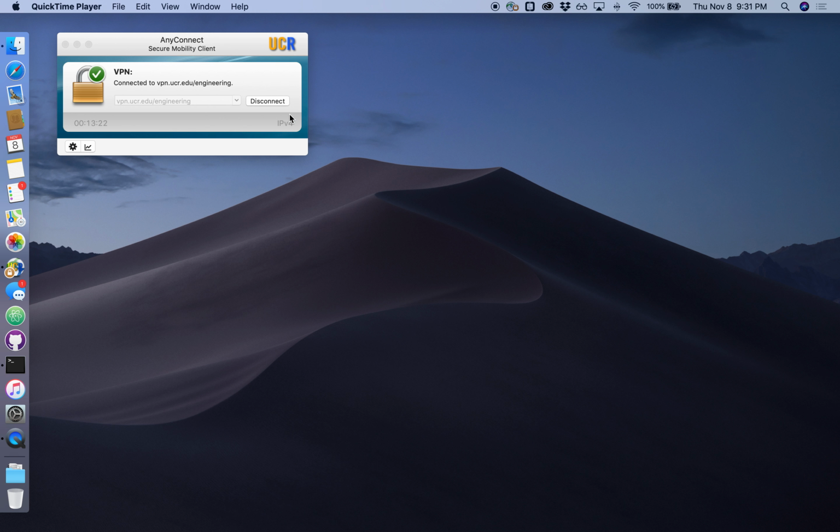Hi, this is the third of the COMSOL videos that I've prepared for Bioengineering 167, Medical Diagnostics. In this one, we're going to combine everything we saw in the first two videos and revisit our model binding-based biosensor, but this time we'll give it a full treatment that combines both diffusion and convection in transporting target to the sensor where it is bound and ultimately detected.